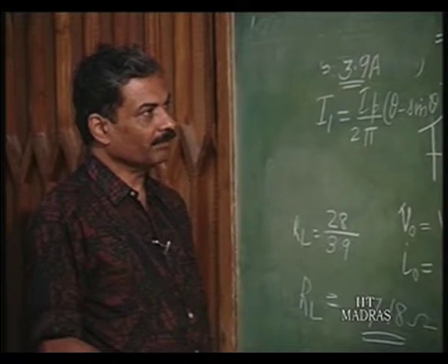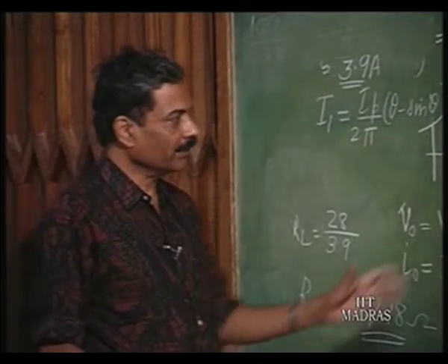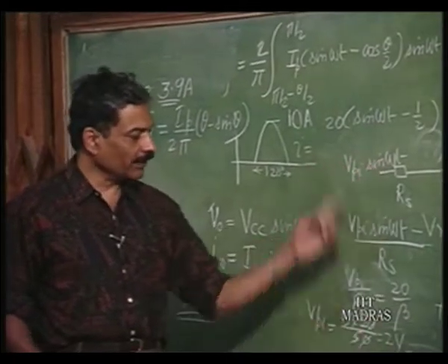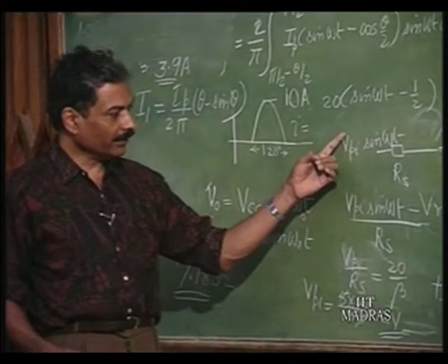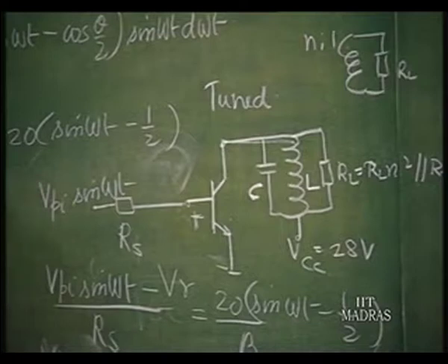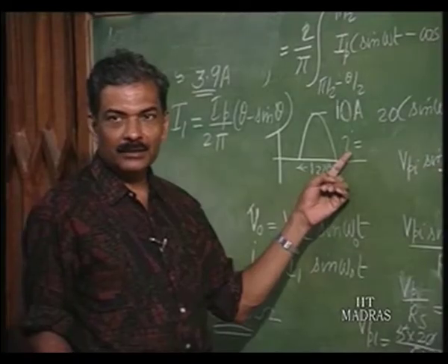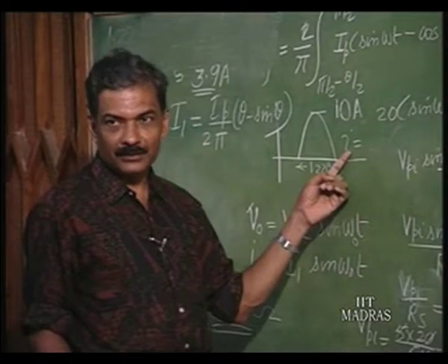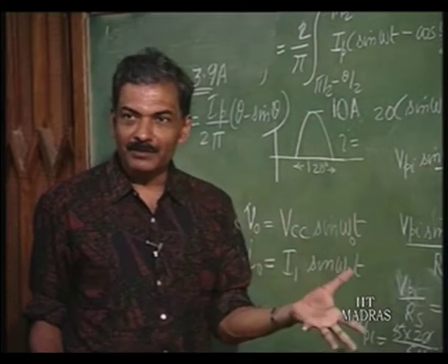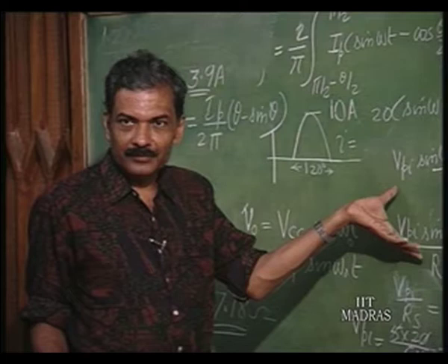This completes the complete design of a power amplifier. So, you must provide this kind of output waveform, V p I sin omega t, that is 2 sin omega t, with current being equal to something like this, 10 divided by beta, that is 0.2 amperes. So, the drive stage should be able to give that much amount of current with peak voltage being 2 volts.